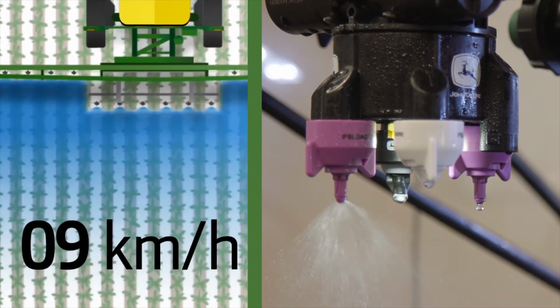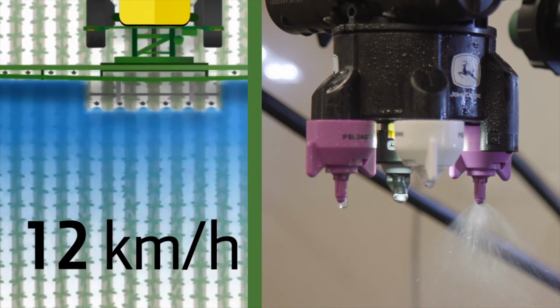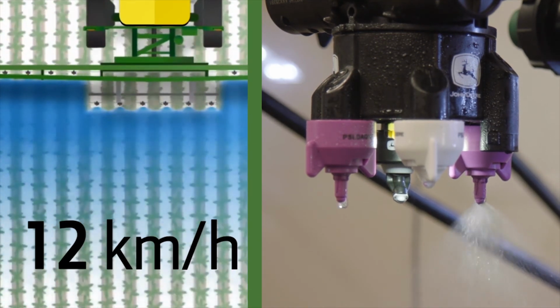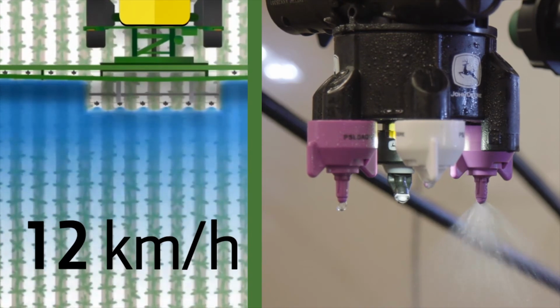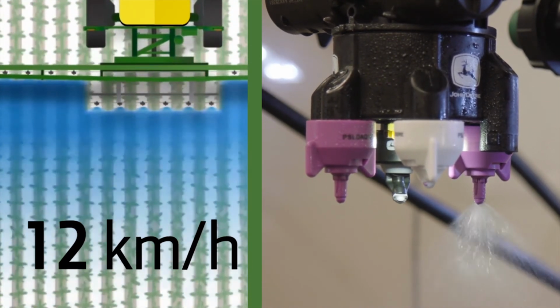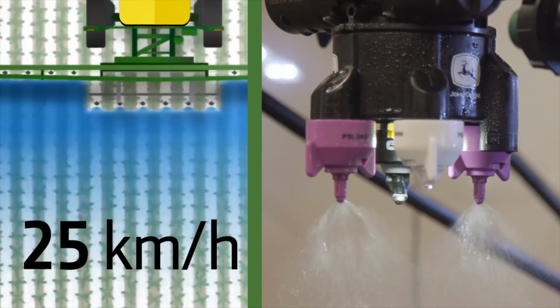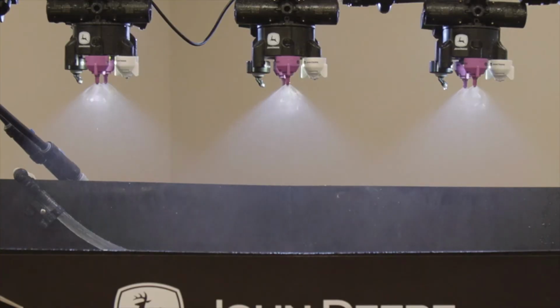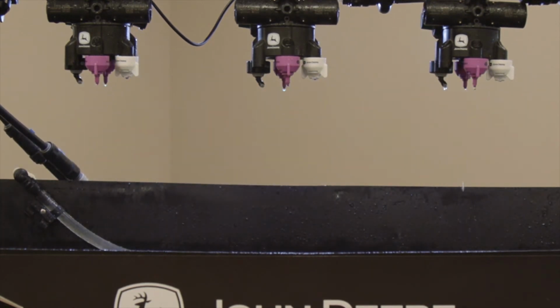So we see as we increase speed, we flip from the front nozzle to the back. As we increase our speed, our pressure is going to increase again, and then to maintain the proper pattern that we want, we're going to kick both nozzles on, which is going to allow for a higher flow rate while minimizing the pressure out of each individual nozzle, giving us ultimate flexibility to select the proper nozzle and the pressure that we desire.